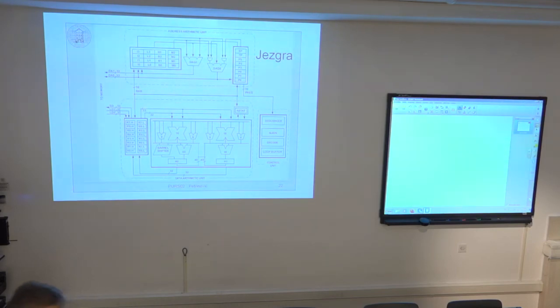In this case, this multi-ported cache can supply all 3 output values, data from the first space, data from another address, instruction from the 3rd address in the same cycle, if they are stored in the cache. If some of those addresses is not contained in the cache, then really it must go outside to the main memory and fetch the actual value from the memory to the cache and to the core. But if you are lucky, if this address is already contained in the cache, then it is supplied directly to the core without any loss of cycles.